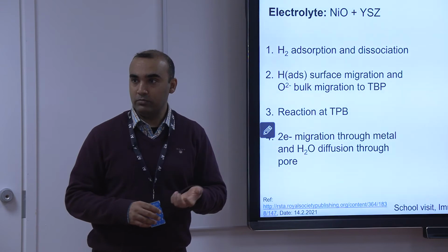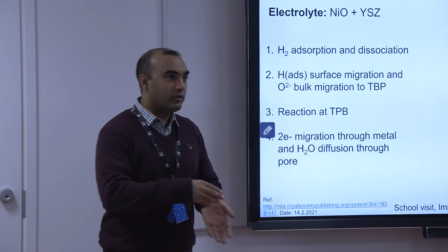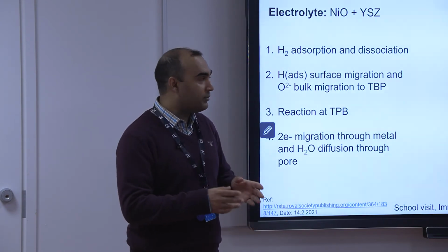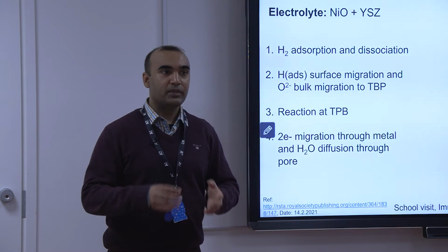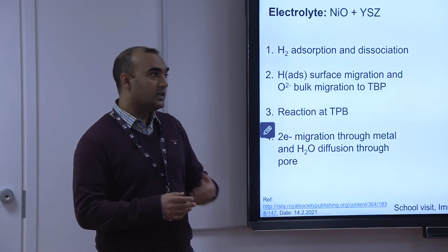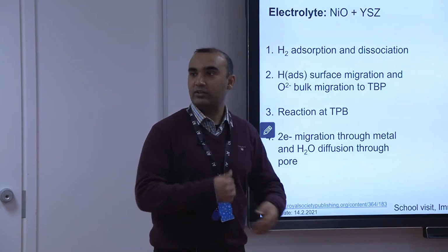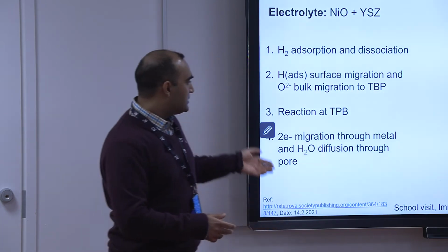And the water which is formed, we need to make sure that this water also leaves the space, because if we have too much water, it will flood the fuel cell. So we have to make sure that it's a porous structure, and the water which is formed needs to also leave the space there, so that the reaction can happen efficiently.